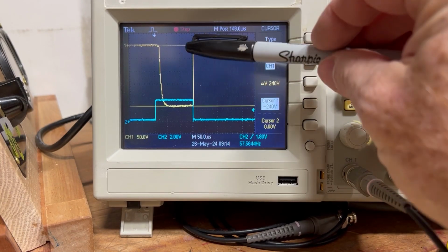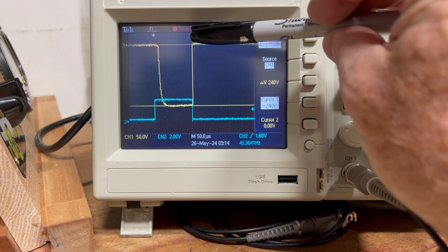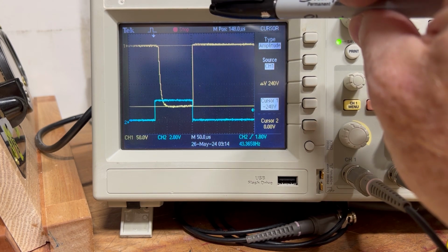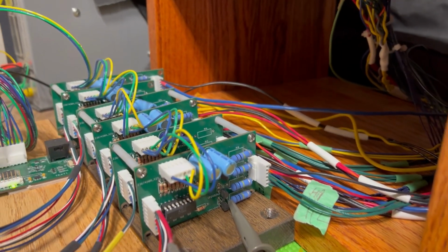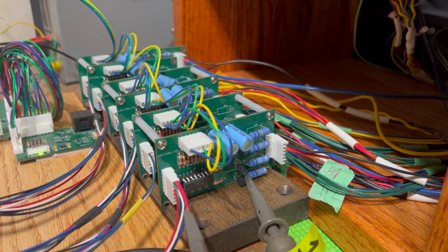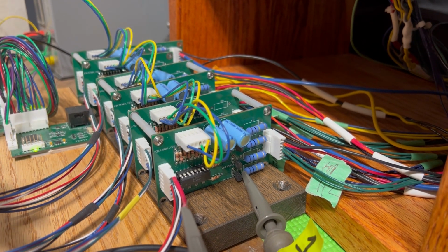The shutoff is much sharper because I'm shutting it off, returning this to ground by turning on that MOSFET transistor. So there we have our selector bar drivers and decoders, sort of in a nutshell. So this is our decoder driver setup for the selection bars, how we do this. That's it for video 2. So thanks for playing along.